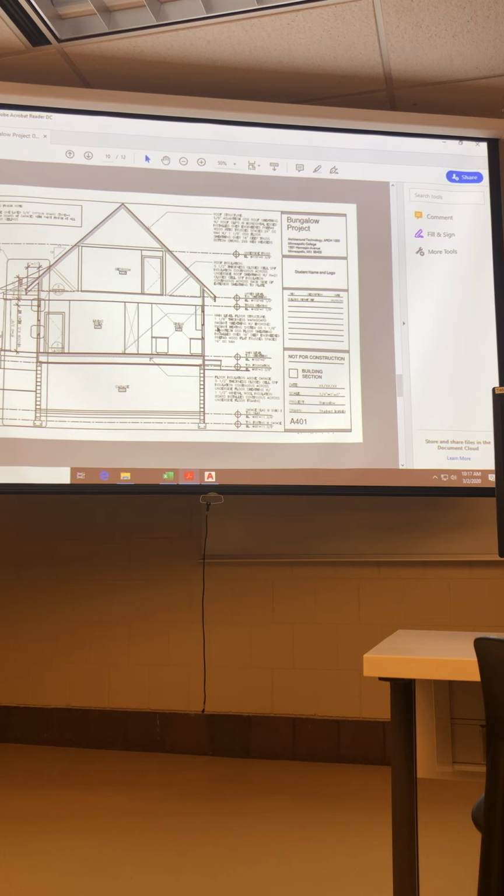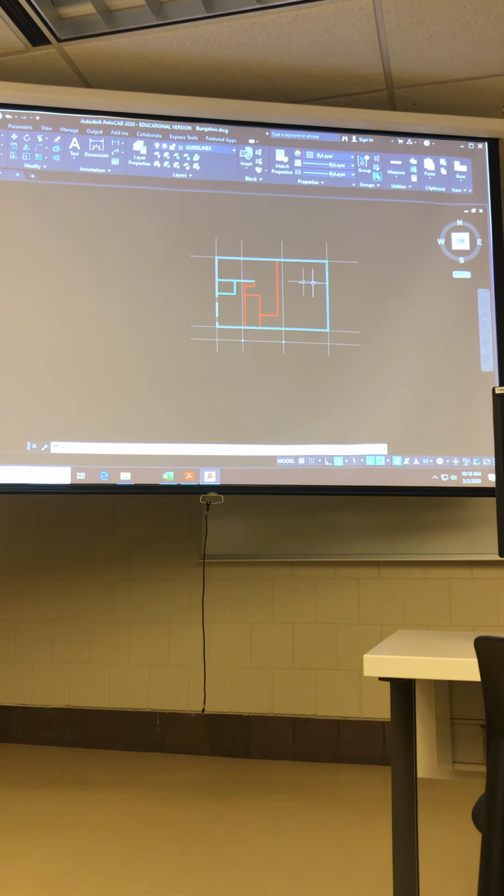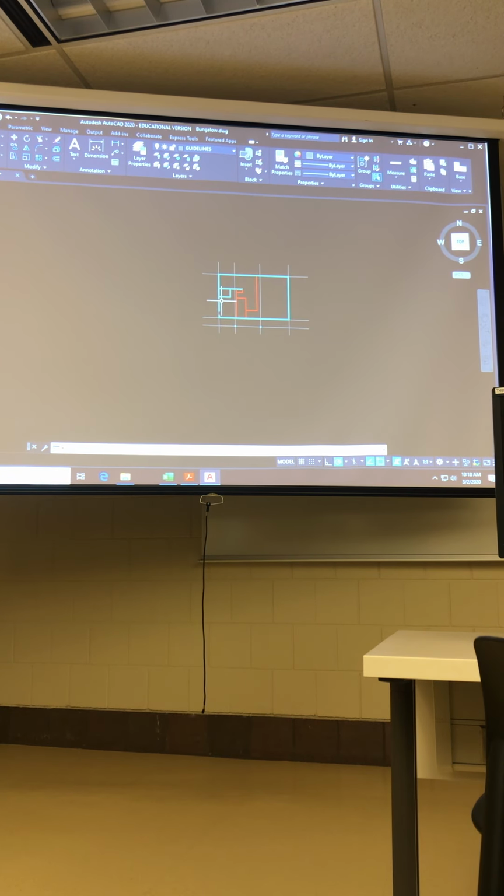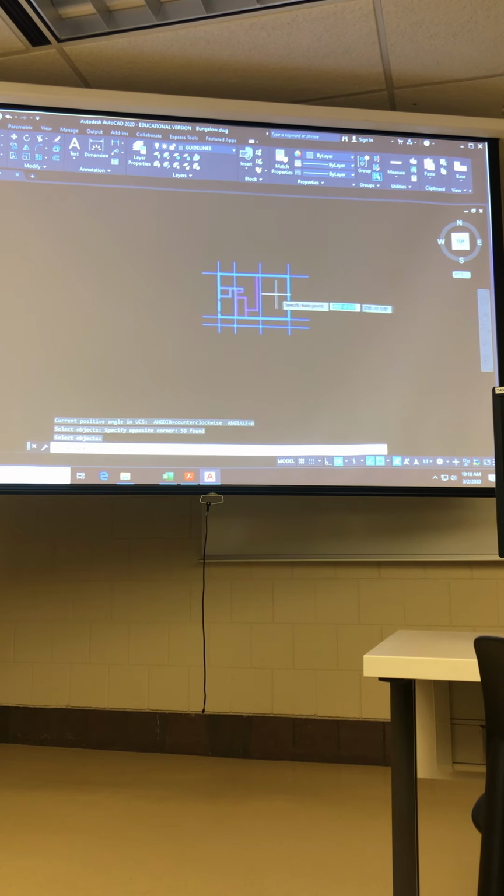That's where we'll begin. When we look at this drawing, again, it's cut through the living room and the kitchen and the garage and the bedroom. If I go back to my AutoCAD drawing and cut through this way, so that I'm drawing it as I can see it actually is, the plan isn't oriented in the right way. So to start with, I'm going to go ahead and rotate my plan so that it is oriented the right way.